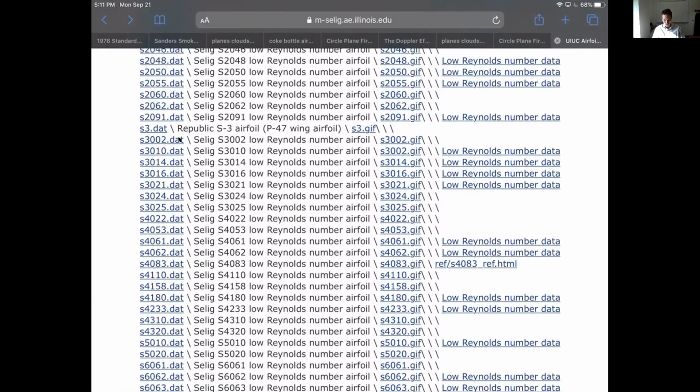And another consideration you might look at is thickness, right? You want an airfoil that's maybe not too heavy, but also stiff enough. If it's too light, it may be too floppy. If it's a really thick airfoil, it may add a lot of weight. We'll see later that for many aircraft, transport aircraft especially, thicker airfoils are actually lighter, but in this case, where most of you will be using a foam wing, that's not going to be the case. A thicker airfoil will be heavier. So you want to make sure that it's a reasonably sized airfoil as well. So anyway, these are just some things to look at.